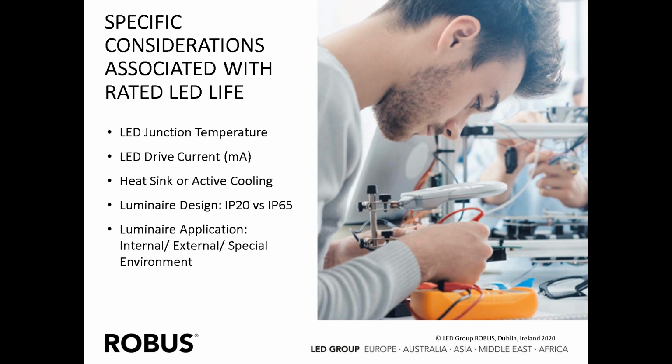Also, we have to look at heat sinking, whether it's a passive heat sink or active cooling, where maybe we have a fan to keep the internal component parts cooler. We also have to look at the luminaire design, whether it's IP20 or IP65, because this is going to have a bearing on the heat that's inside the product.